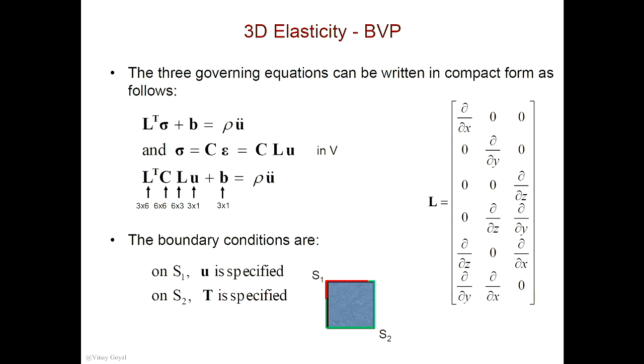You can model a composite ply, a single ply, with this approach, with 3D elements. In each ply, you specify the orientation and the 9 engineering constants. So you model every single row, each row being 1 ply of elements, and you can do that. But it's computationally expensive, so you go to shell elements, which I'll cover in the next lecture. Okay, so with that said, we're ready.